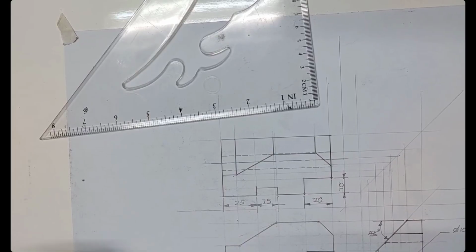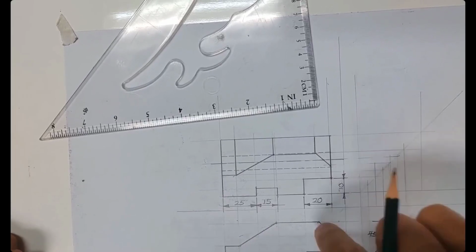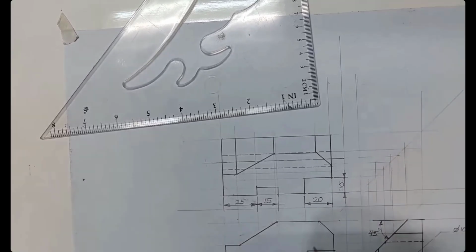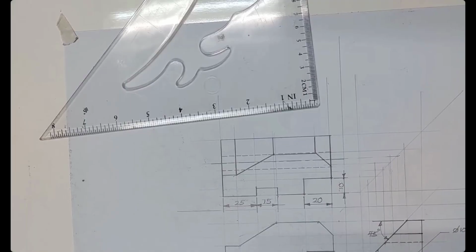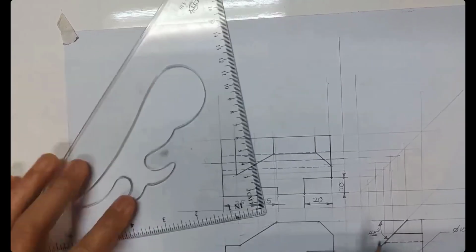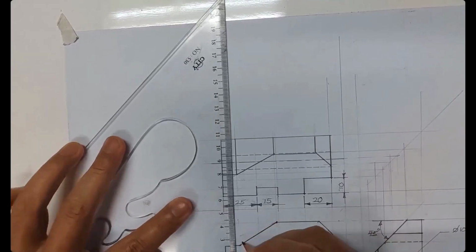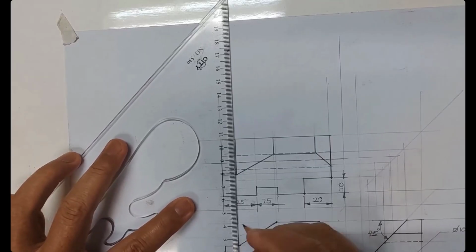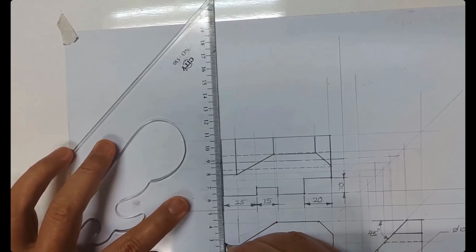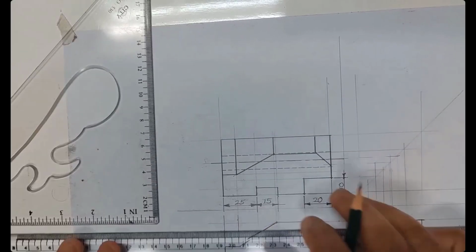This width is 40. I already show it because it clearly shows the features of the 45 degree cutting, to show the 45 degree cutting of the 10 by 10. Can you see this one, 10 by 10? Put it on the front view, because it is clearly cutting, showing the chamfer of 10, and also at this cutting. To show the profile of this feature of the chamfer, the dimension is 10 from here. You have to show it clearly defined from here to here. You can show the dimension because it clearly shows the profile of the chamfer. You can do it like this.